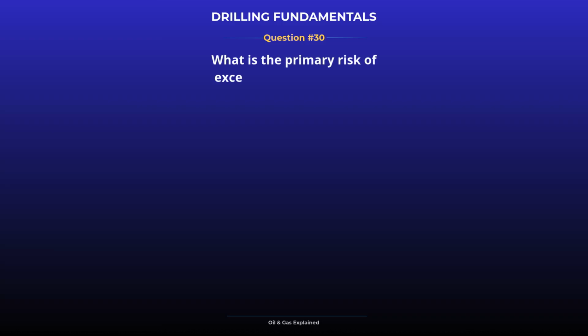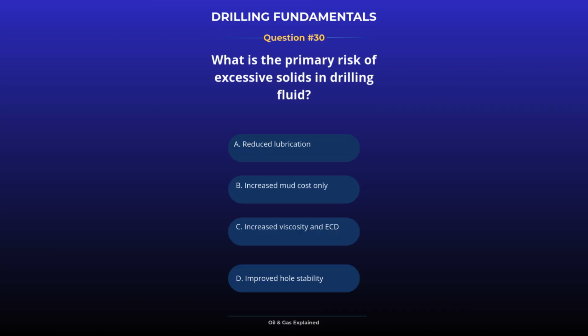What is the primary risk of excessive solids in drilling fluid? Excessive solids raise viscosity and ECD, increasing the risk of formation fracture and losses.